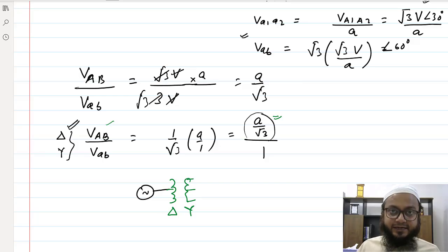If I'm energizing from the delta side, the star side would be the high voltage side, because for the line voltage we have seen that the turn ratio is multiplied by root 3 times, right? So I would be using this delta star conversion for stepping up the voltage, and this star connected transformer is feeding the transmission line at higher voltage, because this can be easily designed for the high voltage side.